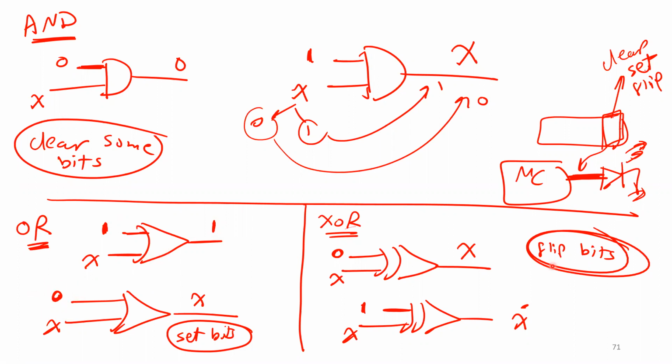So very easy, right? For example, in this example, this pin is associated with this bit. Now I want to turn the LED on. All I have to do is put 1 here. So how can you put 1 here? And again, don't change the other ones, because the other ones are connected to something else.